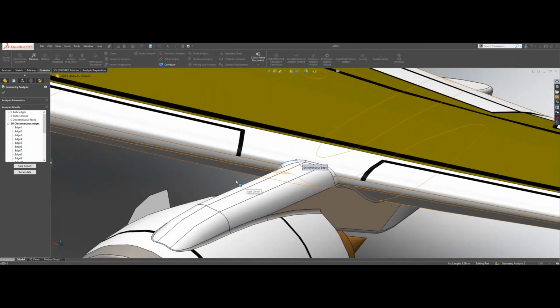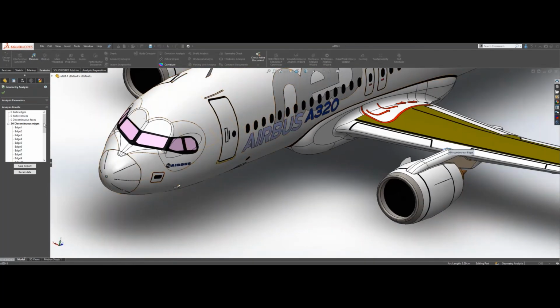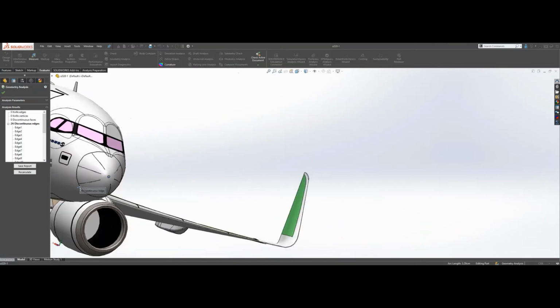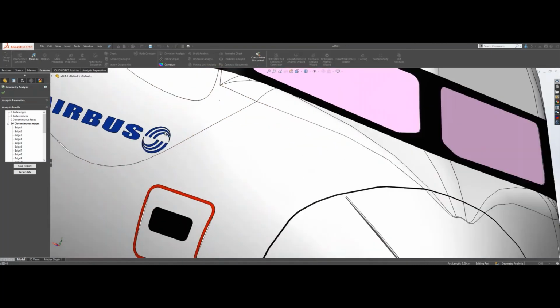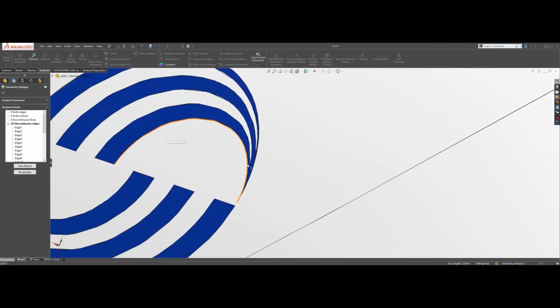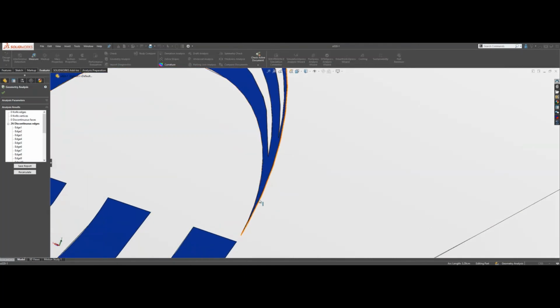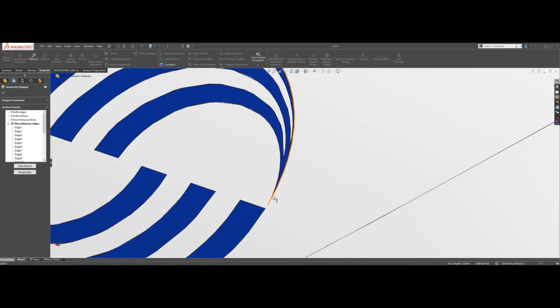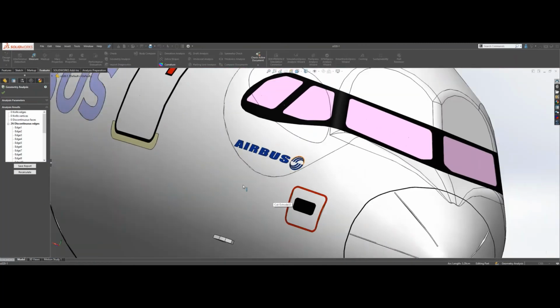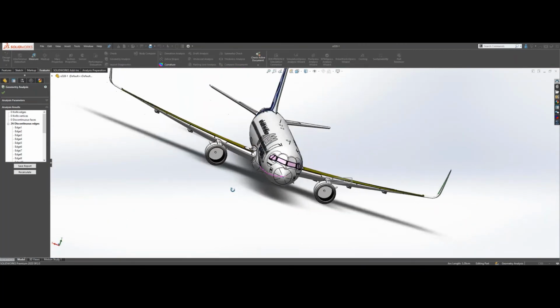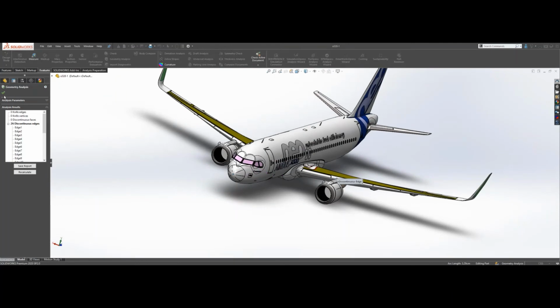Okay, and even though it didn't find them, I actually want to show you just a quick thing on what could be considered a knife edge. Okay, so perhaps whenever you have these 2 edges, right, coming in together, there could be a portion where they could actually come in between. So that can also be considered a knife edge. Okay, and knife edges, usually the endpoint tends to be what is called a knife vertex, right? So this is sort of what it can look like in your model. Okay, so perhaps that is part of your design intent, or perhaps it isn't.